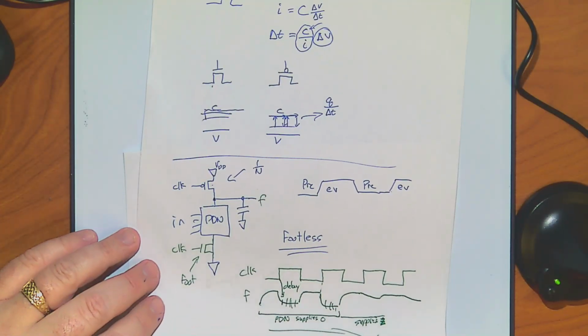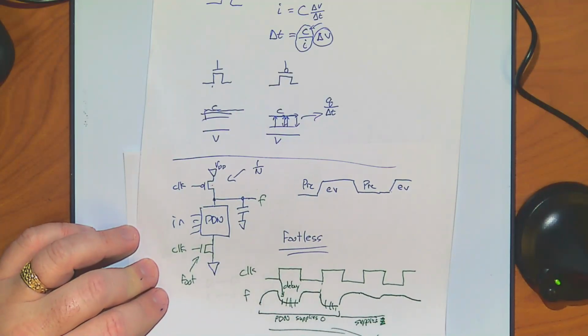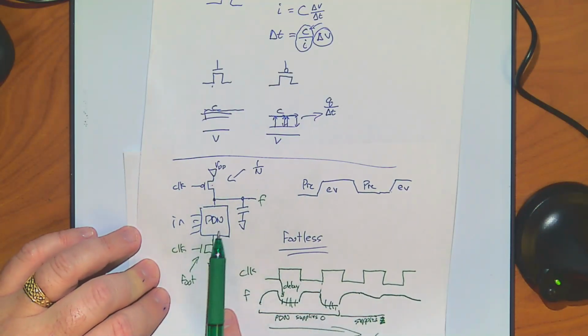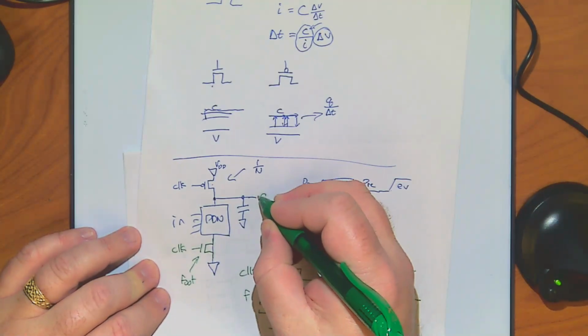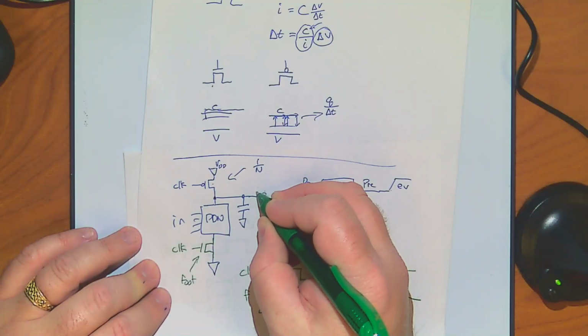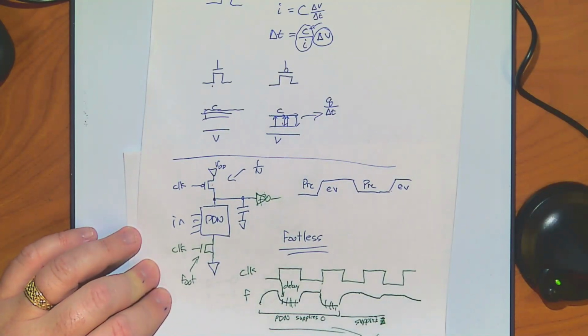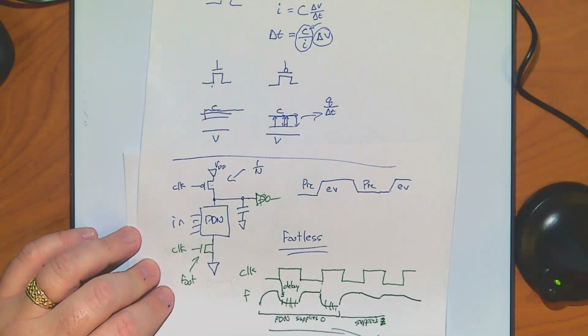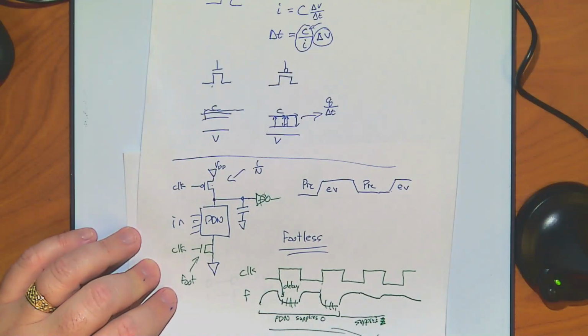But again, like I said, it's essentially this, right? You remove the pull-up network, you keep the pull-down. All you do to get a domino logic onto this thing is you put an inverter. Now it's a domino. And one domino feeds to the next, and they just keep triggering very, very fast. Usually only the first one needs a foot. Usually all the rest of them are footless.